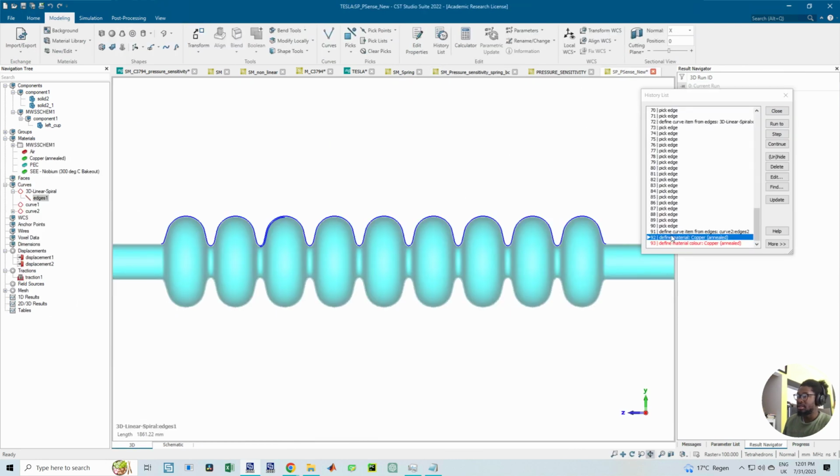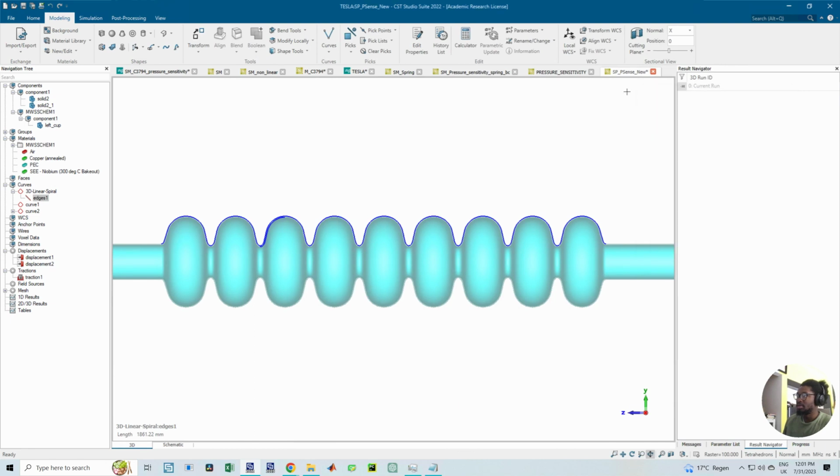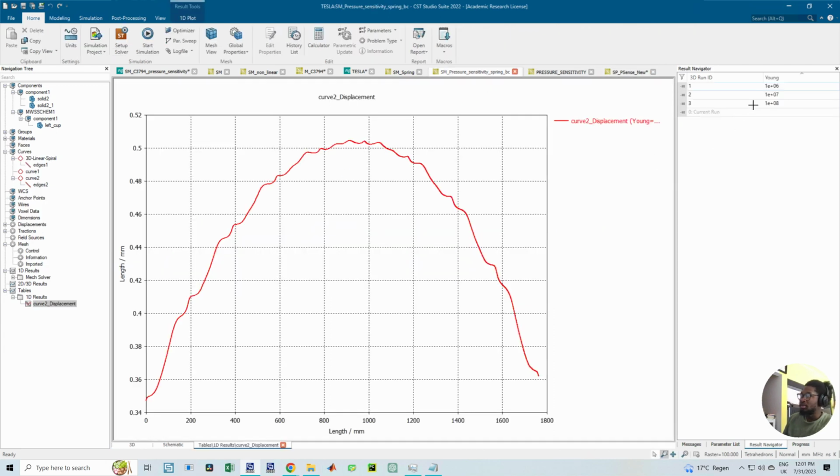So this is the displacement you have along this surface. This is the displacement field plot. Along this line, this is the displacement that you have for Young's modulus of 1e6. Now you could calculate with the analytic formula. Although in the previous video we didn't quite get good correspondence, I have run the analysis before and compared the numerical, detailed analysis with adaptive mesh, with everything really set up, and got the same result.